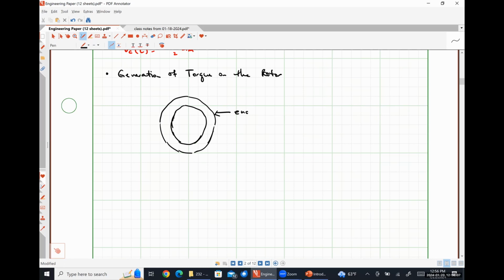This bit right here is an end ring that's holding the structure together. And then we're going to have two conducting bars that are 180 degrees out of phase with each other, right? So this is a conducting bar, and this is a conducting bar. And deep into the board, there's another end ring so that we have a closed loop, okay? So we have a ring, two bars, and then another ring so that current can circulate around that closed path.